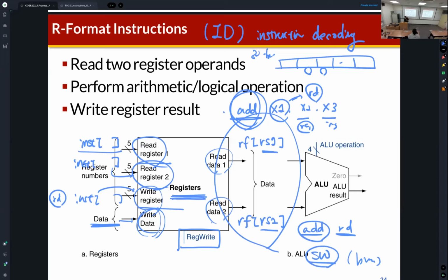That's why the register file has the read write port, and this read write port is the control port. And it's easy. If the read write becomes 1, it means that register write is enabled, but if it is 0, then register write is disabled. Okay, so this is the register file.